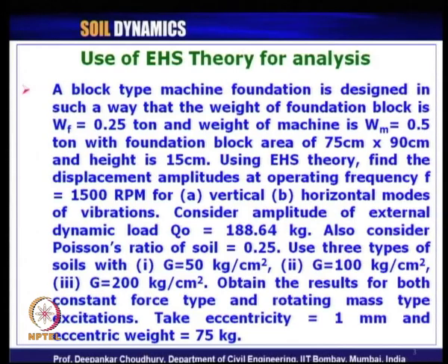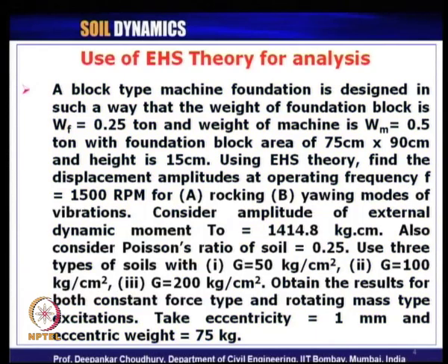We had seen the application of EHS theory for the analysis and design of machine foundation, to compute the displacement amplitude at operating frequency for vertical mode and horizontal mode of vibration for block type machine foundation, for 3 different types of soil, in case of both types of excitations, constant force type and rotating mass type excitation. Also, we have worked out the example for rocking.